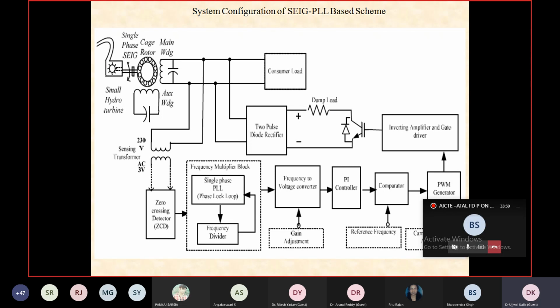So definitely if you reduce the THD, automatically the power factor will be improved. And if power factor improves, the system will require less and less reactive power. Maintenance cost of the system will decrease, because of those harmonic currents a number of rotating magnetic fields will be set up in the air gap of this generator, and that will cause a large number of pulsations in this generator.